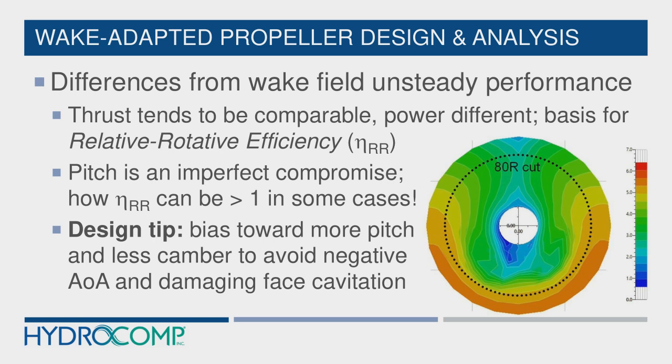Now, a design tip for anybody designing wake adapted propellers is we tend to bias more towards pitch and less to camber. Remember, lift in any kind of foil is a function of angle of attack and blade, or section, camber. So what we want to do is ensure that we avoid any negative angle of attack situations as it rotates, because that can lead to very damaging face cavitation, pressure side cavitation.